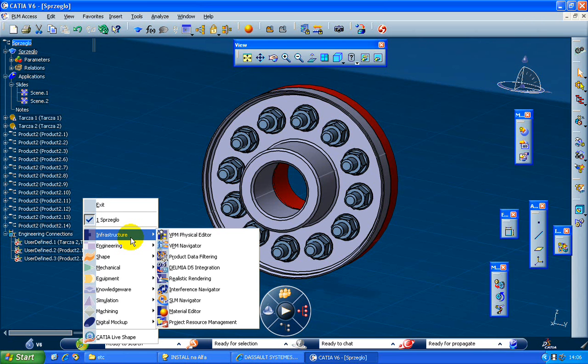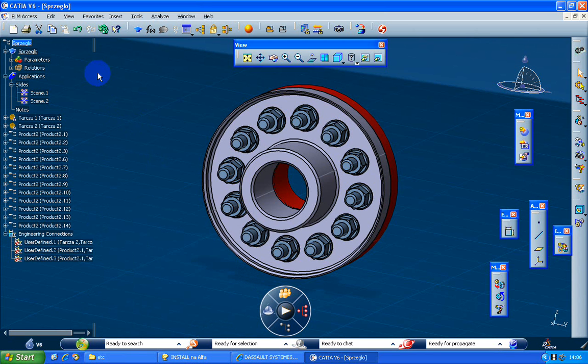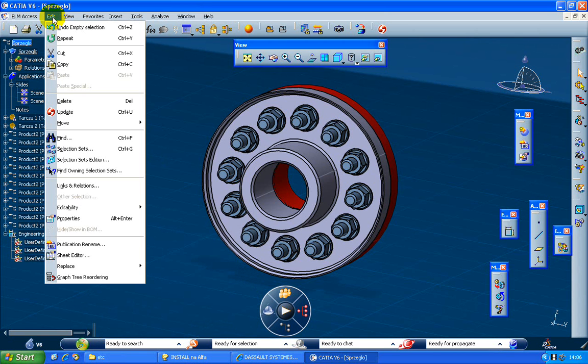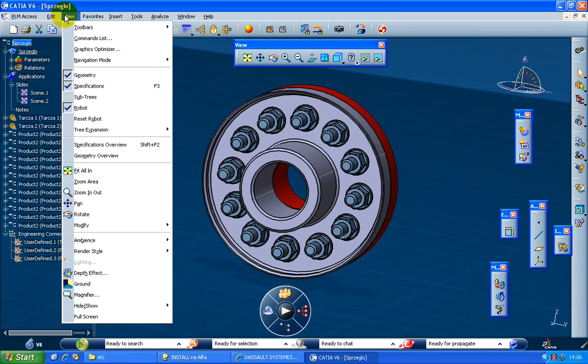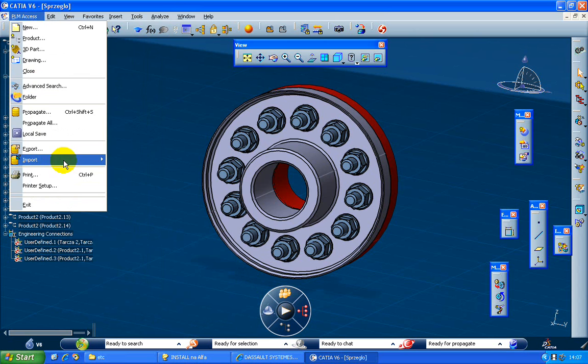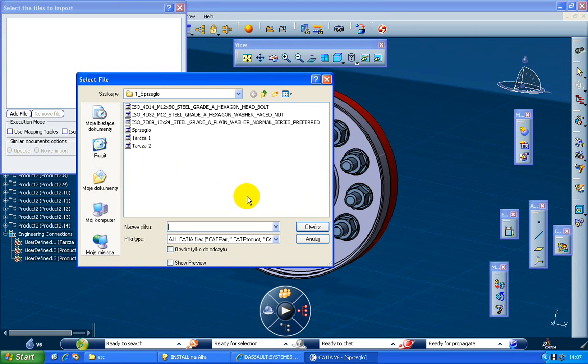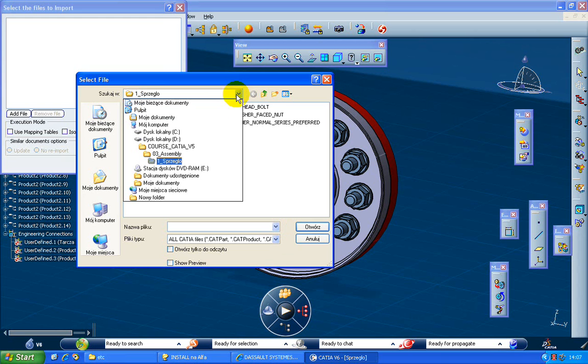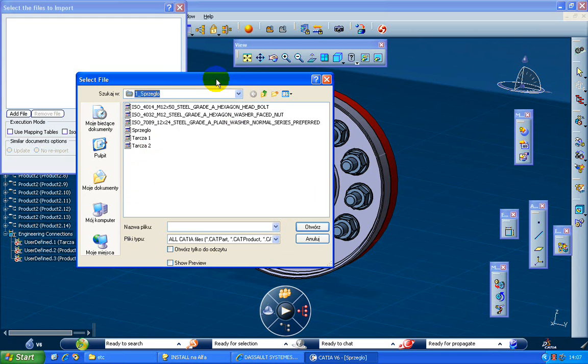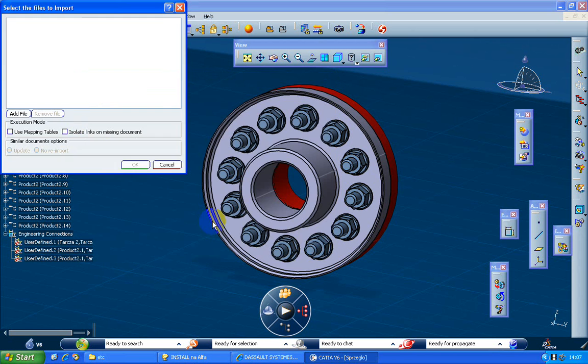Okay, I will continue with the PowerPoint. We have seen how it works. You select the part you want to change, and you have different information in the window which appears. First, choose the transition. Of course, CATIA filters for you the list of possible transitions which can be performed on the selected part, 3D part, or assembly. You select one status from the list, and you click on OK.